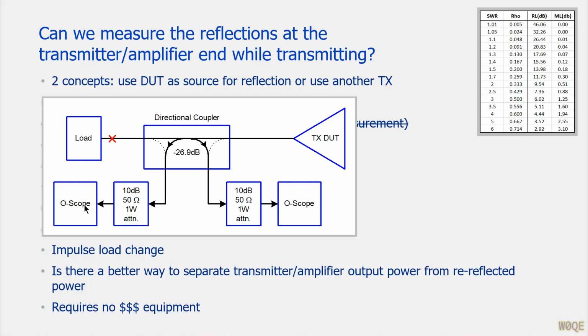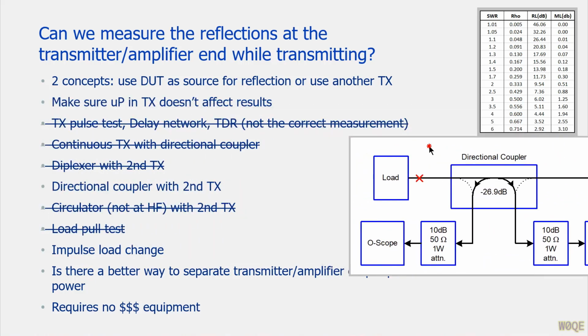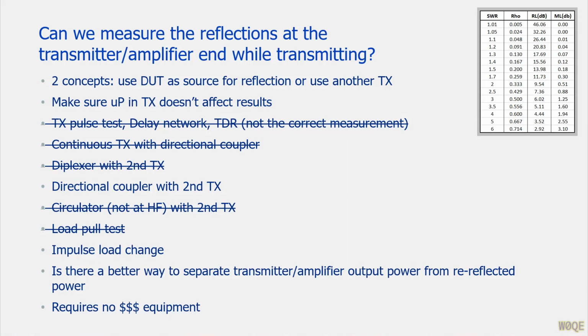So remember, I'm capturing this all the time. I start the trigger when I release the relay, so I need to trigger for at least a couple milliseconds at a pretty high sample rate to see everything that's going on. The scope I have has 14 megapoints of storage, which is plenty to get several milliseconds worth of delay at still, say, a 20 nanosecond or 10 nanosecond per division sweep rate. So this was another way of doing it. Both of these ways seem to work well. I got similar answers on both ways.